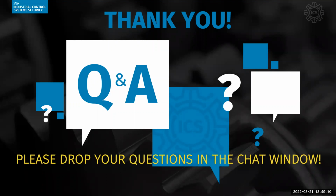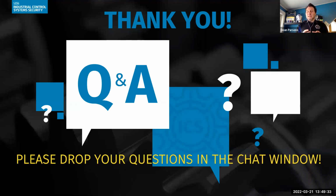Okay, another question is, which data source would be a priority first? Windows OT logs or the network traffic first? Yeah, another great question. And we kind of touched on it a little bit in this session where we talked about, so many times, getting the OT security event logs, getting the OT engineering application logs. But if I could only pick one, I'd love to pick two, but if I could only pick one, it would be the network, because you at least understand what connections are going to and from. And if I had an ideal state, back to the previous question, I could get the full packet captures. I would prioritize the network first, because the adversary usually has to get there across the network.